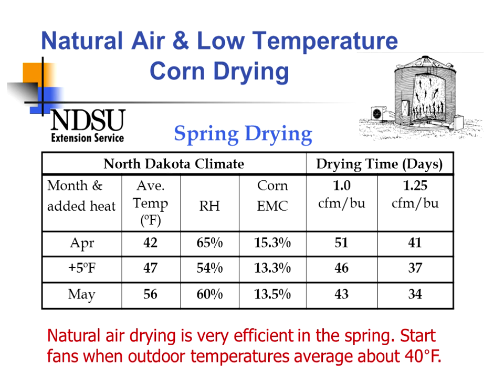What I recommend for a lot of farmers is to hold that corn cold over winter, bring it down to temperatures right around freezing, hold it over winter, and then in the spring, when we start seeing temperatures up close to 40 degrees on average, we can turn the fans back on and do the drying. And when we look at climatic conditions across the country, what we will see is that spring drying conditions really are pretty good.